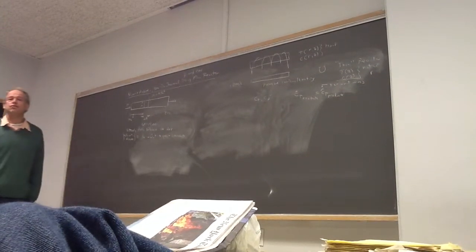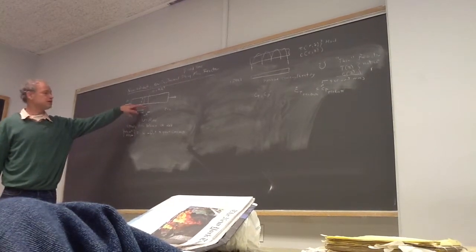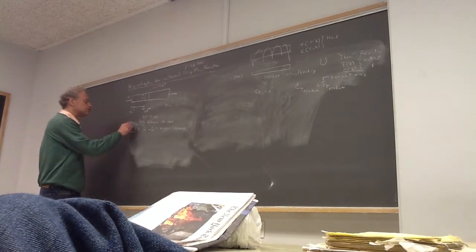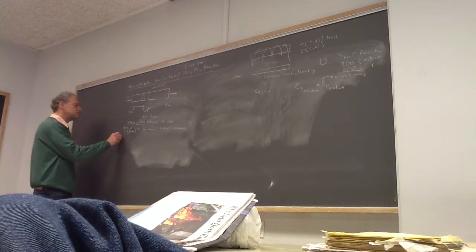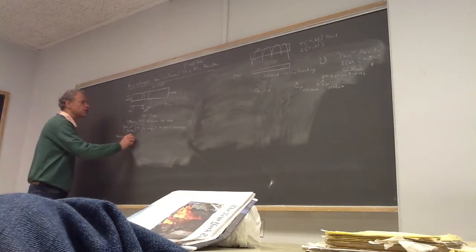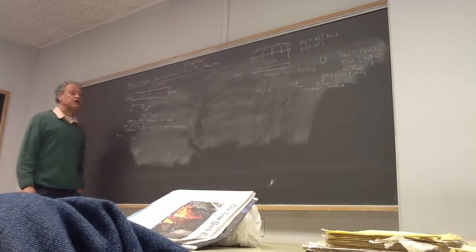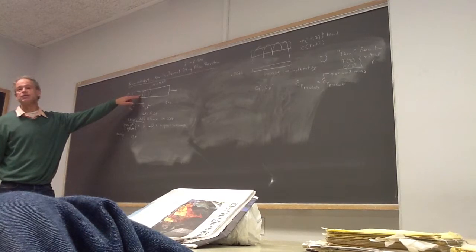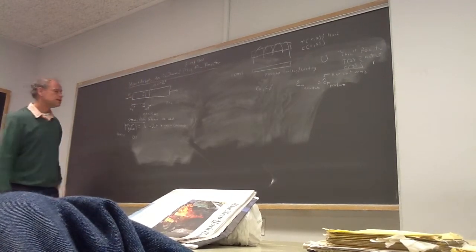Okay, so let's do a mass balance, and let's do it on this delta V. This is a steady state mass balance, so I'm going to neglect this. For a mass balance, I have 0 is equal to in. Well, what is in? The in for species A. Since I'm only worried about species A, I'm going to use Ca. So what is in?